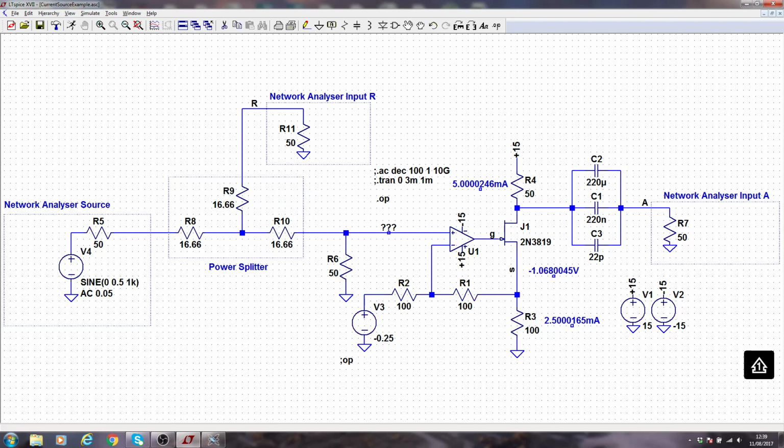If you put it on a node, it will tell you the voltage on the node. So I try to put one somewhere where there's something useful. There, it's going to be minus 250 millivolts, and sure enough that's what this DC source is providing. F5 for delete, and then a right click to get rid of the delete. Also escape works fine.